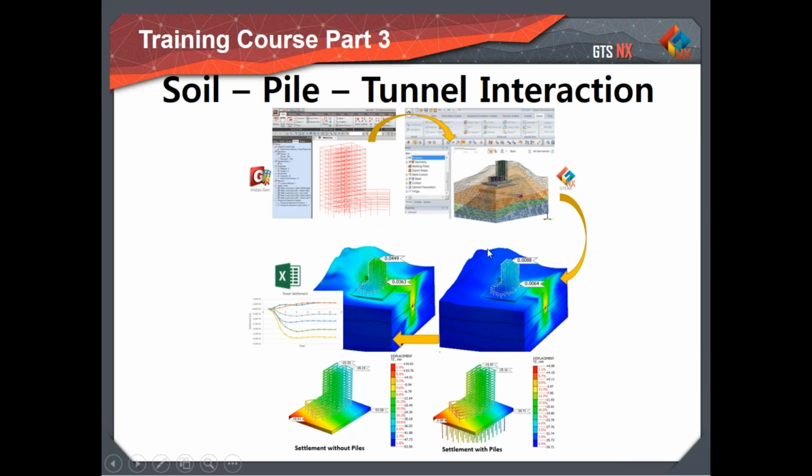And what we'll be doing is this building will also have piles included. And we'll do a comparative study. We'll do 2 cases. Everything else will be the same, except in one case we'll have the piles, in another case we won't. And using Excel or the internal graphing capability of the program, we can compare it differentially, if you will, and design the foundation to not allow it to exceed a certain limit of settlement based on this new consideration.